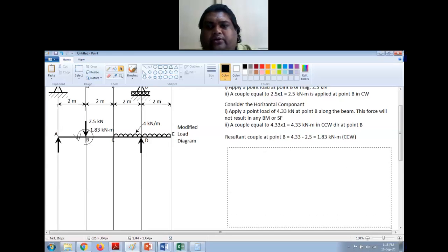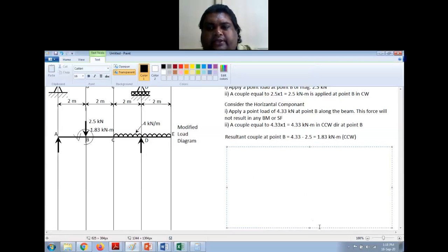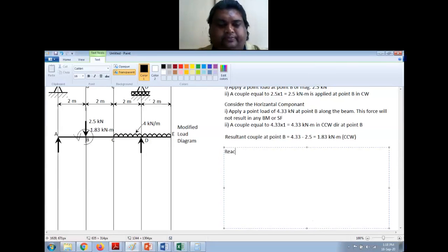So what you have to do first, you have to find the support reactions. So let me first take bending moment about point A. You have the sign convention.